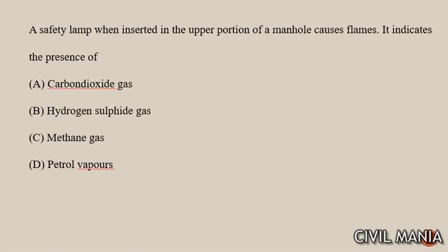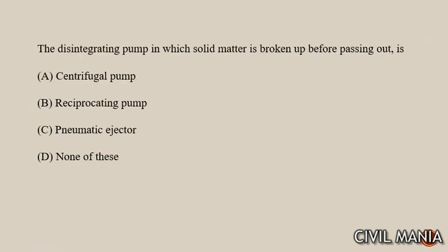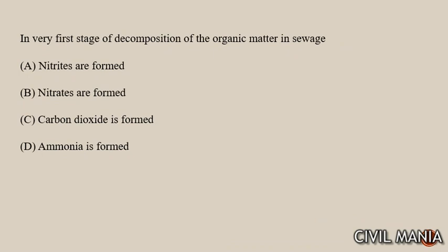Next question is, the safety lamp when inserted in the upper portion of the manhole causes flame. It indicates the presence of methane gas. Next question is, the disintegration pump in which solid matter is broken up before passing out is centrifugal pump. Next question is, in the very first stage of decomposition of the organic matter in sewage, ammonia is formed.